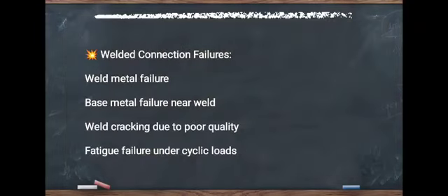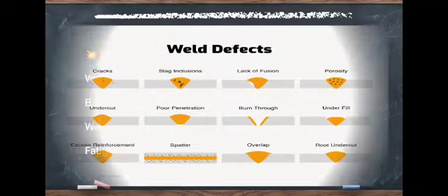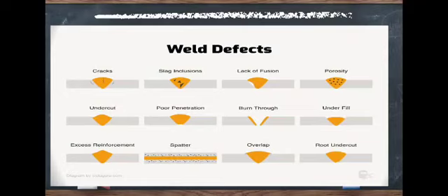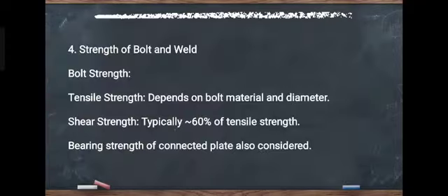Welded connection failure. In the welded connection, it may fail by weld metal failure, base metal failure near the weld, cracking due to poor quality, and fatigue failure under cyclic load. The weld defects can be seen here.